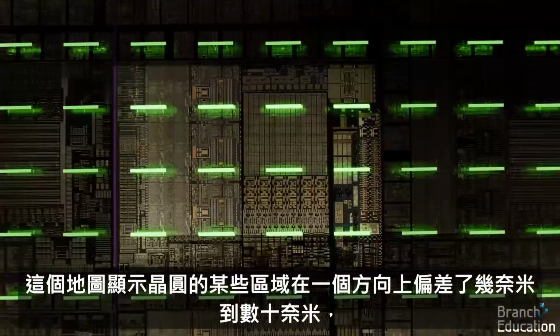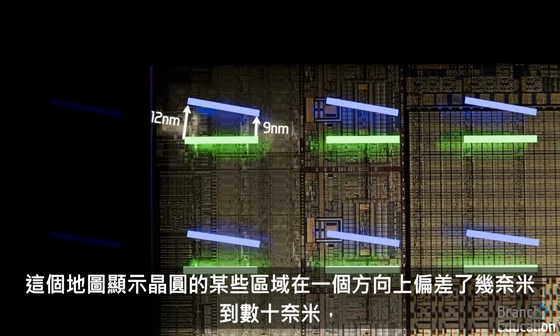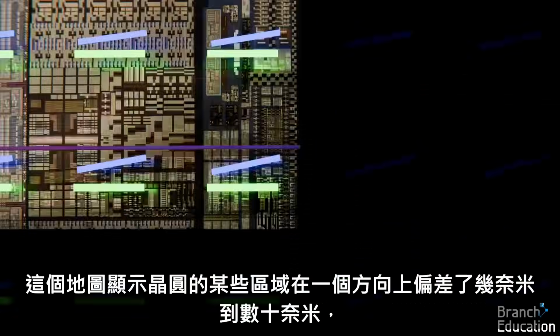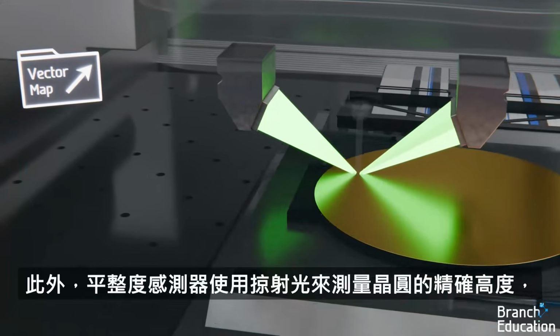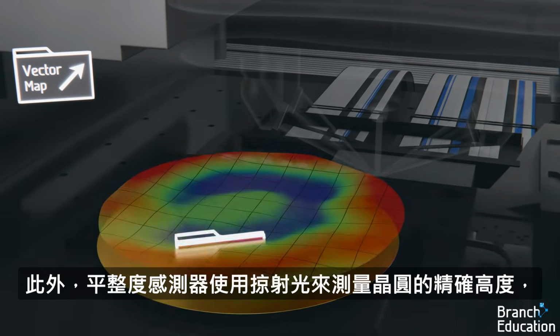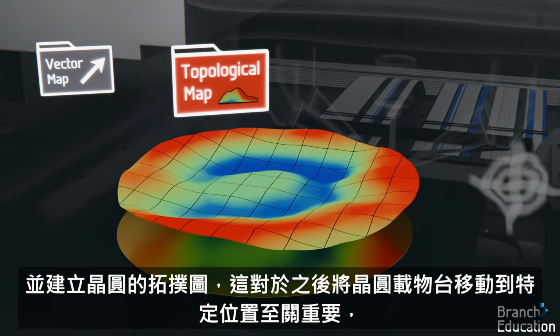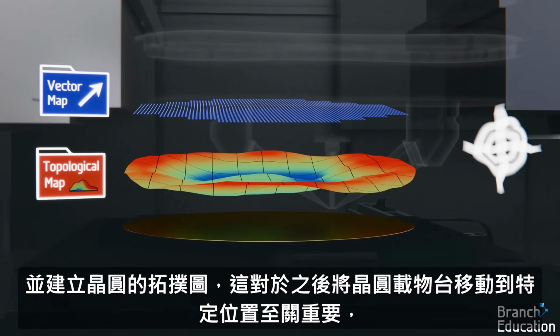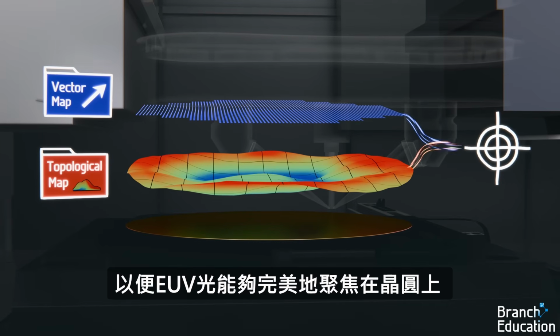This map shows some regions of the wafer being biased in one direction by a few to dozens of nanometers, and another region being biased in a different direction. Additionally, the leveling sensor uses grazing incident light to measure the exact height of the wafer, and builds a topological map of the wafer, which is critical for later bringing the wafer stage to the position such that the EUV light is perfectly focused onto the wafer.